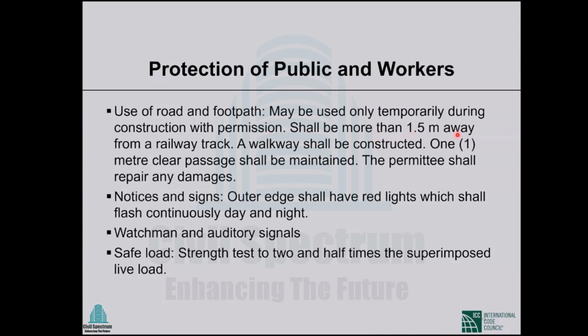it shall be more than 1.5 meters away from a railway track. A walkway shall be constructed so that people can take a detour. 1 meter clear passage shall be maintained, etc. So we need to have permission, and there are other requirements that we have to meet, things like that.